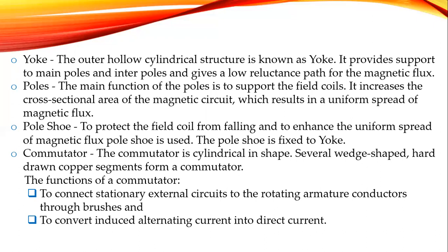Commutator. The commutator is cylindrical in shape. Several wedge-shaped, hard-drawn copper segments form a commutator. The functions of a commutator are to connect stationary external electric circuits to the rotating armature conductors through brushes, and to convert induced alternating current into direct current.